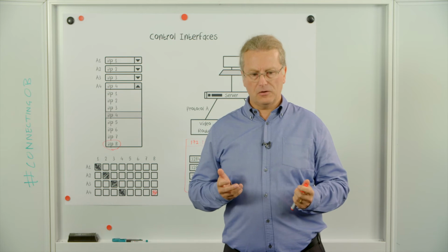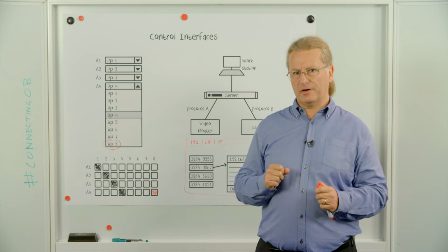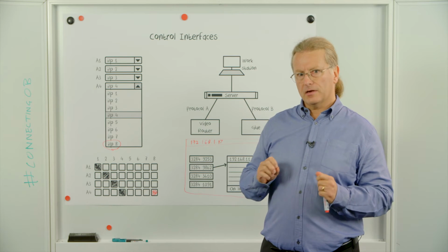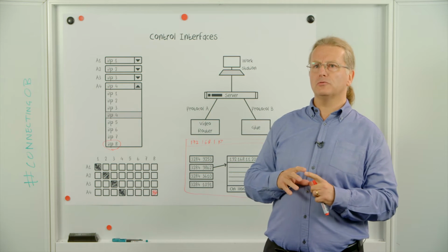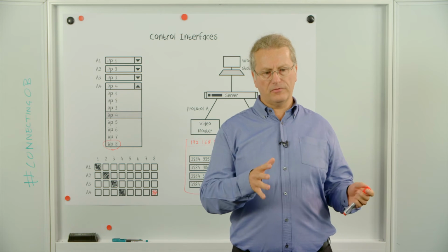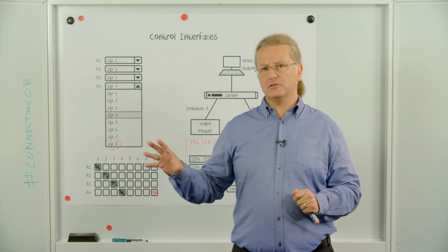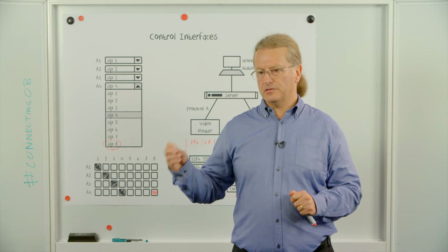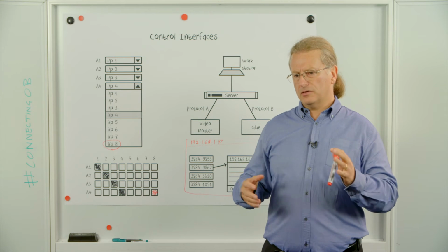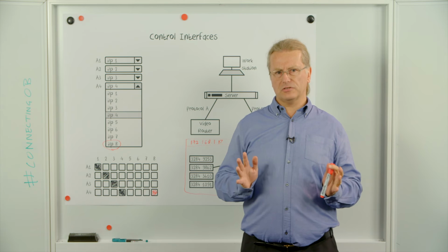If the system is slow, it's very likely the operators will stop using the control system and go back to using the manufacturer's interfaces. And the same can be said if you don't install the system fully. If you put a partial interface in where only some of the equipment is being controlled via the control system and other parts are still using the manufacturer's interface, this is going to lead to confusion and also possibly a position where the operators just ignore the control system altogether.